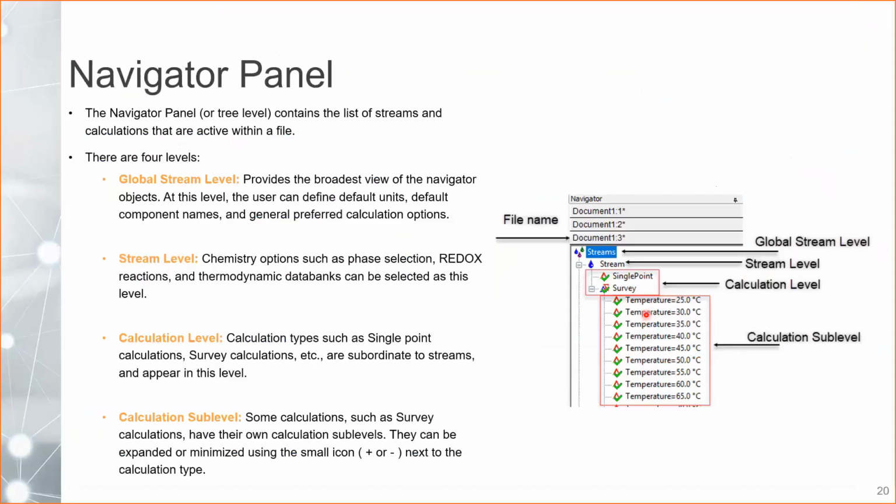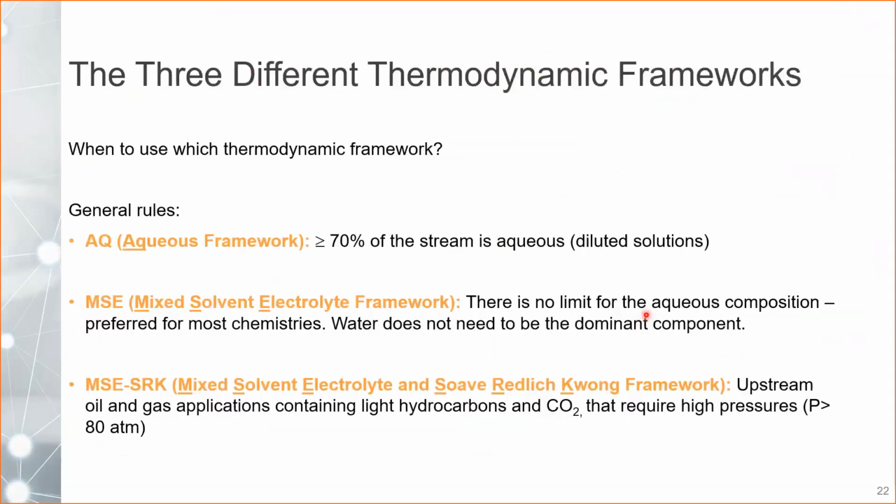Okay. So this is what we already saw, and I will give you all of this for your information. So as I was saying, and Mike was saying, there are 3 thermodynamic frameworks. This is a slide that I have created just for reference when to use which thermodynamic framework in your simulations. As a general rule, I have found that if you have more than 70% of the stream is aqueous, or basically you have a diluted solution, then you can use the AQ framework to calculate your electrolyte properties.